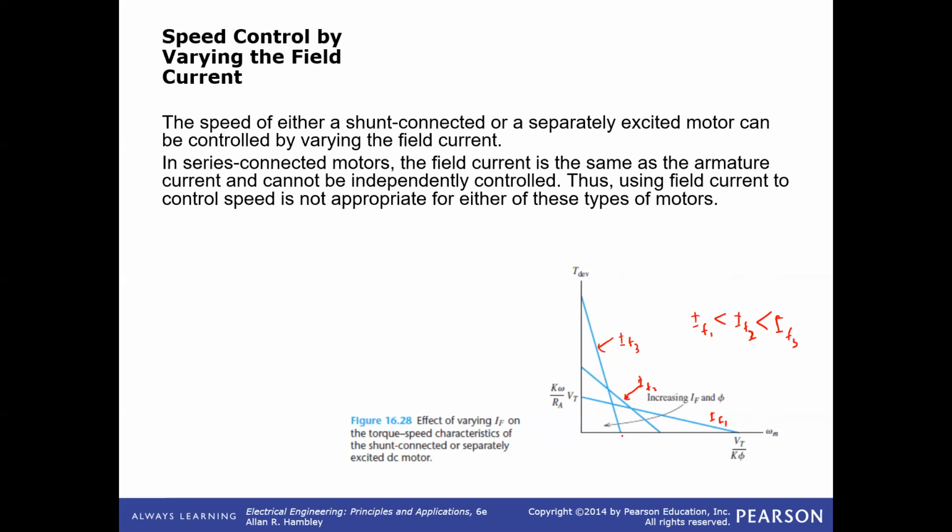So if you increase the IF, you will see that the slope will increase. Okay, so this can be applied for shunt connected and separately excited motors. Okay, but in series, this type of control is not appropriate.